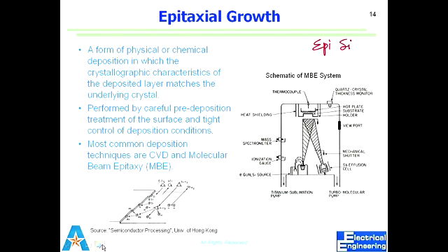But now, the differences are recipe and the underlying crystalline structure. And there is a specialized equipment called MBE, molecular beam epitaxy. We had one MBE here in Nanofab. I think that's decommissioned. It's a very complex equipment, but gives you exactly the same film grown on top of what you already have below.